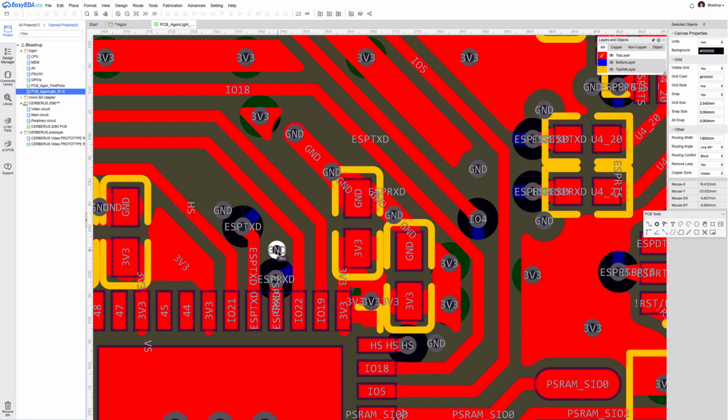But in the process of finding something, it will spread itself and interfere with the other signals and reduce your signal integrity. You get this common mode energy, and in this case you don't want the common mode energy because these signals now are not differential signals, they are independent ones.